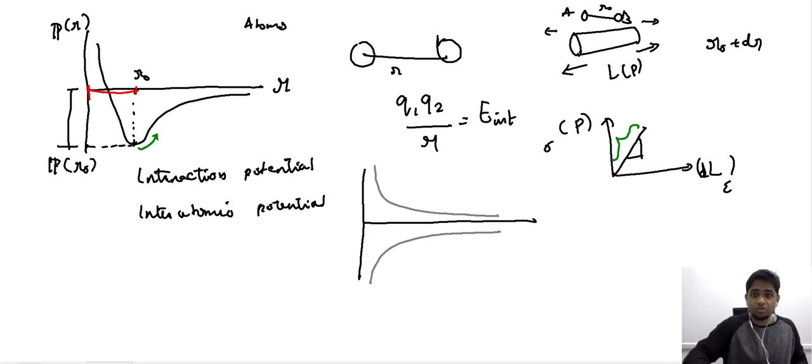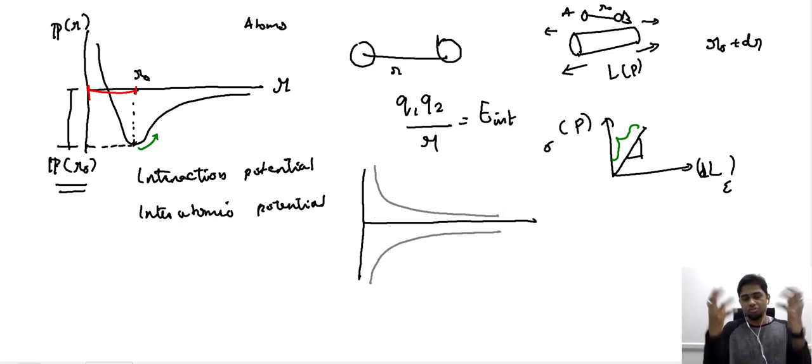That is because you are playing with the interatomic space, the bond length. You are increasing the bond length and the distance separating the two atoms, which increases the interatomic potential. When you release it, the system wants to go back to its stable state, to reduce the interatomic potential, and it goes back to this energy here, ultimately corresponding to its original state.